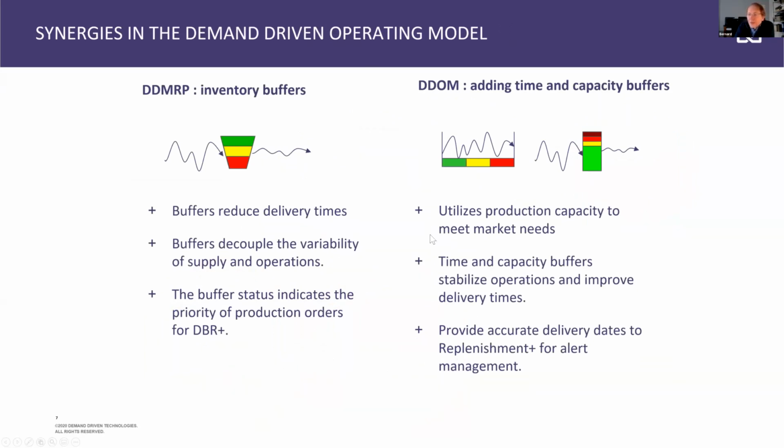In order to get there, we complement the inventory buffers Ziad alluded to earlier today, and we add two additional mechanisms. One is what we call time buffers. You can see time buffers as queues, because in any manufacturing environment you do have queues at some steps. But instead of having queues that just accumulate because you're pushing material, you organize time buffers.